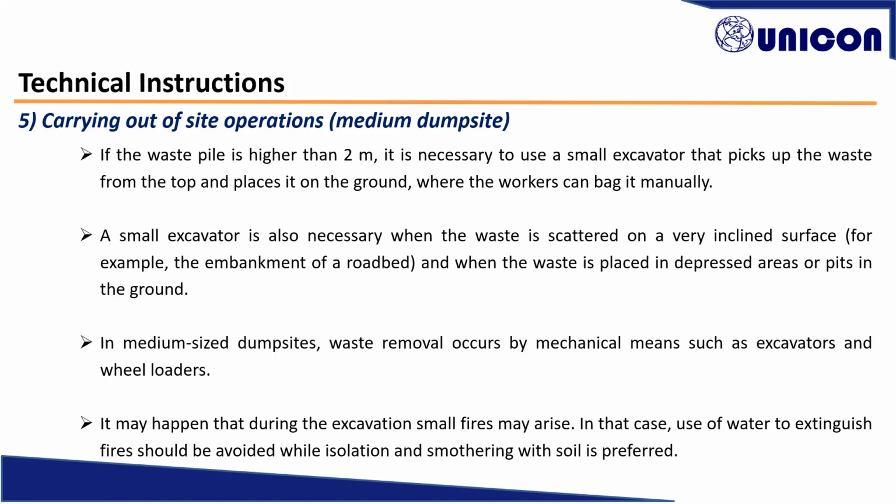In medium-sized dump site, as we said before, waste removal occurs by mechanical means, such as excavators and wheel loader, in order to increase the waste removal rate. It may happen that during the excavation, small fires may arise from the dump site. In this case, use of water to extinguish fires should be avoided, while isolation and smoothing with soil is preferred.